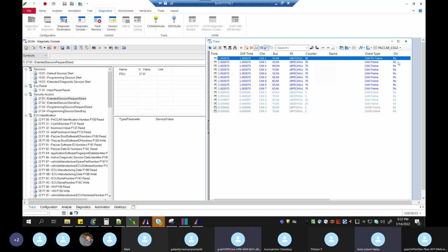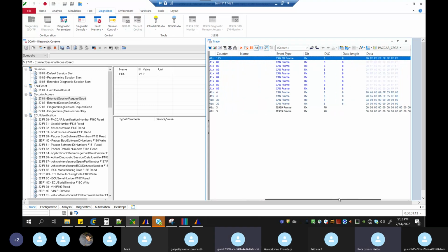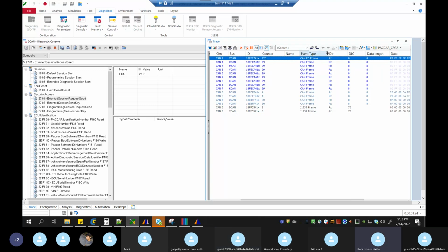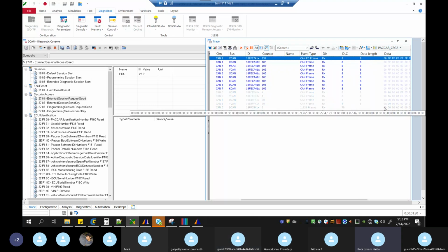which we are expecting to transmit every 1 millisecond. In such a way that what we have done in the coding is that all these messages should be transmitted from our ECU immediately once we start the ECU, every 1 millisecond or 1 second. So all messages should be holding this information. You can see the data also. You can see the direction here. What is the DLC length? What is the data length? What is the data it is holding? All those things.